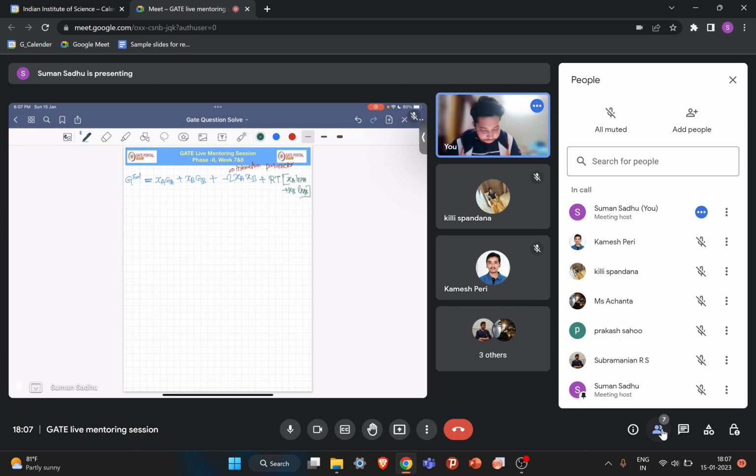So now what was the equation for ideal? Okay, let me just rearrange, first the entropy term, in terms of ideal solution, and then it will be easy to understand. XA ln XA plus XB ln XB, and then that delta H in XA and XB. So in case of your ideal solution, only up to this part was there, right? This part was for the ideal, and this part is your excess over ideal. So this is the G of solution for the regular solution model.